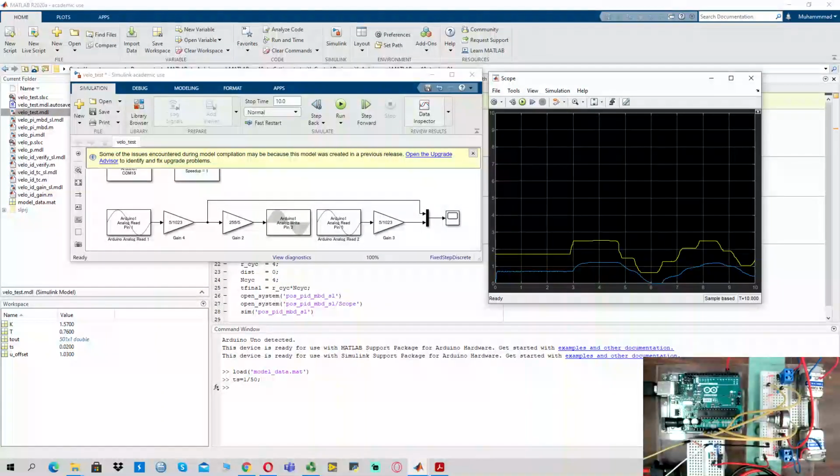I just wrote it here as well, that the output is detected by a sensor, which in our case is the tachometer, and compared to the target value that we have set in the simulation files. Depending on the deviation, the control input is generated by the proportional control, and that part which determines the control input from the deviation is called the controller. The controller's responsibility is to generate the control input to drive your system.